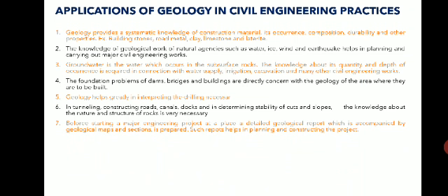So all these types of words you must be familiar with. You must know what is limestone, how it reacts with water. If you know all these terms, then only you can read the report properly, right? They will give you maps also, cross sections: at what location the rocks are inclined, at what depth, what is the height of the rock, what type of soil, what type of rock. Suppose granite is written, sandstone is written, you must know what type of rock it is and what properties it will have, okay. So you must be able to read the report, so that will help in planning and constructing your project.